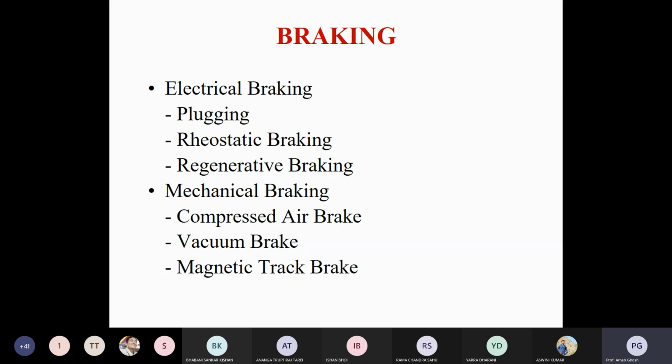So you can see basically most of the important features will be connected below the train, below your locomotive, and on the upper side of the locomotive. But on the upper side nothing big is there, only the pantograph and the electrification, meaning how the power supply comes from the pantograph to the air circuit breaker. Then one cable is there, and that cable is connected to the auto transformer of that locomotive.